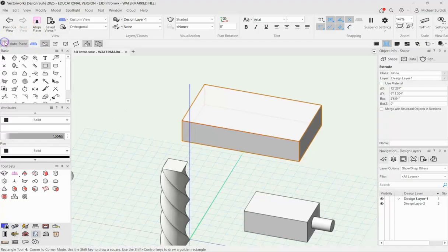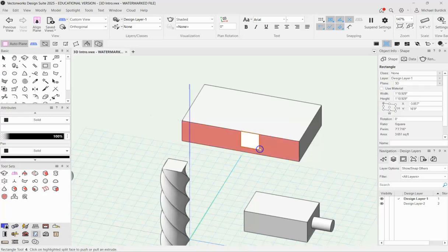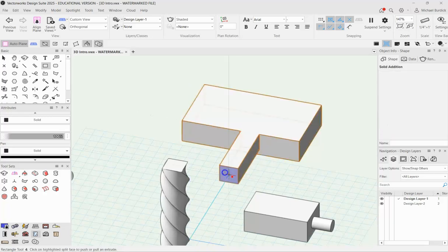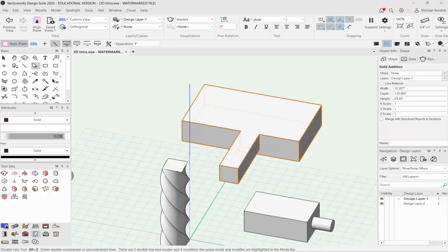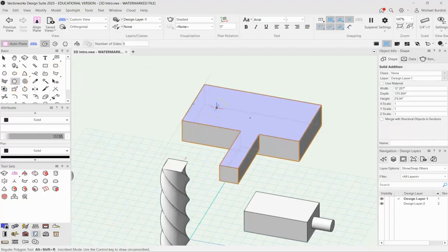Let's go to automatic here. If you can just float around, pick a surface, draw a shape, and then automatically push-pull. And that'll join the shapes if you have this selected as well. Push-pull isn't available with every single tool. For example, it won't work with double line, but anything that has like a regular polygon or a polyline, so your rectangle, rounded rectangle, circle, oval, polyline, polygons, all of those, this will work for.